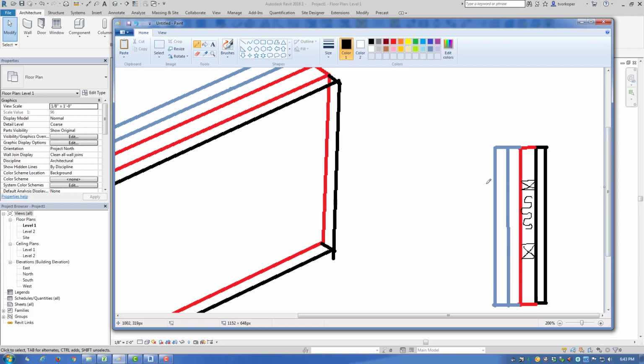The reason being is you don't hardly ever see them when you're looking at a model or the drawings that are created from the model. You only see the studs in detail cuts and maybe some section cuts. So therefore, the way we most often draw in Revit is we create the wall like Revit does with a plane, and then as soon as we get a detail or a section cut, we fill in the studs and the insulation with two-dimensional line work.